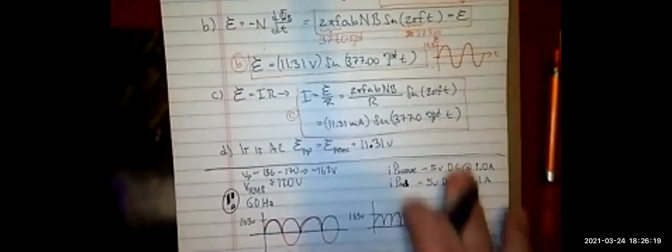So the first thing we're going to do, before we even run to that full wave rectifier, is take this 163 volts and run it around, remember the Pilgrim's belt buckle? We're going to run it around the Pilgrim's belt buckle such that this number of turns is lower than that number of turns. So maybe we'll say this number of turns is 360, just because that's a big number that multiplies everything. I want this to be a step-down transformer, okay?